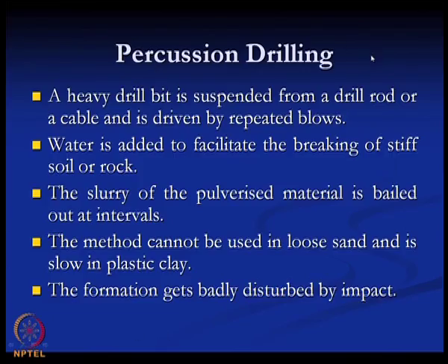Next one, percussion drilling. A heavy drill bit suspended from the drill rod or a cable is driven by repeated blows. Water is added to facilitate the breaking of hard rock or soil. The slurry of pulverized material is removed at certain intervals. The method cannot be used for loose sand and it is slow in plastic clay. The formation gets badly disturbed by impact.